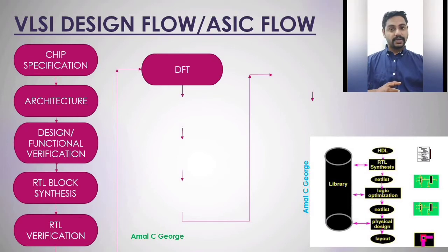DFT consists of several steps. The first step is scan path insertion. It is a methodology of linking all register elements into one long shift register called scan path. This can help to check small parts of the design instead of the whole design in one go.